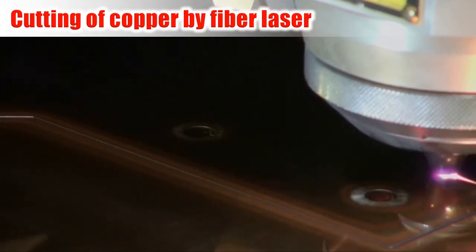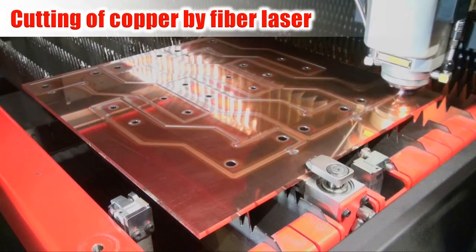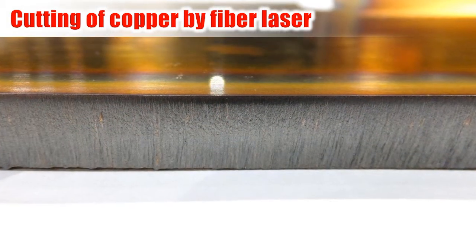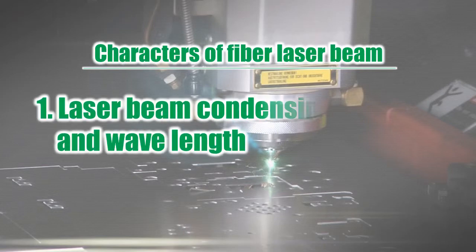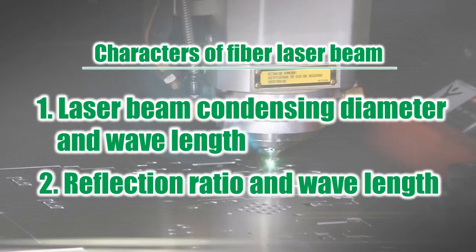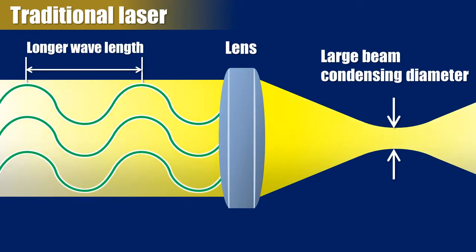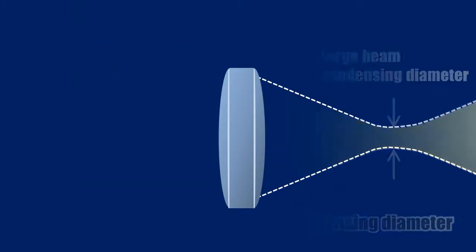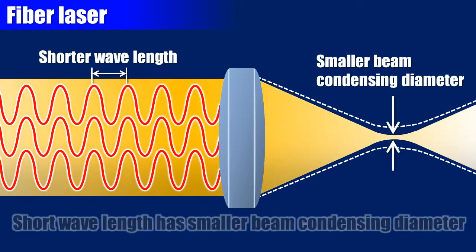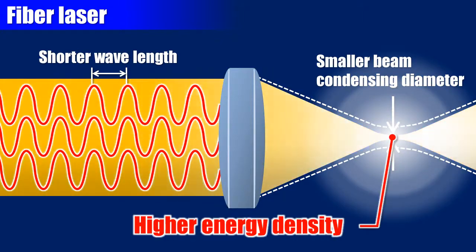As you see, fiber laser machine enables high speed and high quality cutting of copper. This was made possible by the different characteristics of the laser beams. The wavelength of a laser has a correlation between beam condensing and reflective ratio. Let me briefly explain their characteristics. The traditional laser with long wavelength has large beam condensing diameter. By contrast, fiber laser with short wavelength has smaller beam condensing diameter, so the energy density at the focal point of fiber laser is higher.